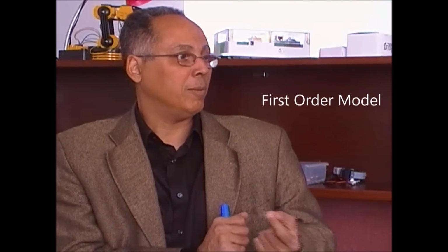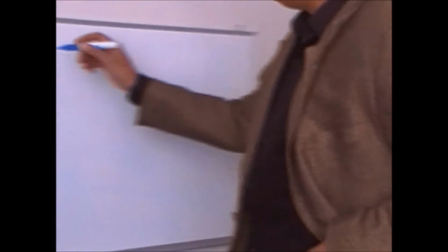So let's take a simple example today. On another occasion we can go to higher orders of identification, but today let's stick to the basics, to the concept. Let's pick a motion control system and identify a first order model for that system. If you have read the textbooks on motion control, you'll see that a motor can be modeled as first order or second order, and some high-speed motors even higher than order 2. Here we're going to stick to first order. It's an introduction to identification. So this is the idea here.